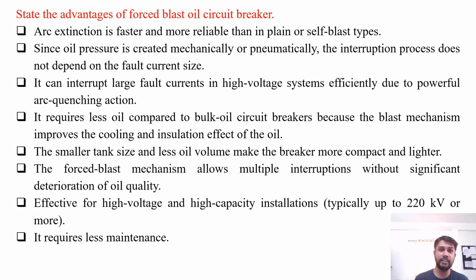State the advantages of forced blast oil circuit breaker. Arc extinction is faster and more reliable than in plain or self-blast types. Second, since oil pressure is created mechanically or pneumatically, the interruption process does not depend on the fault current size or the magnitude of the fault current. Now it can interrupt large fault currents in high voltage systems efficiently due to the powerful arc quenching action due to the external pressurized force.